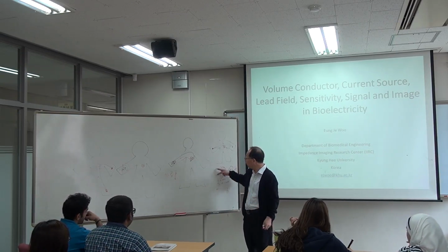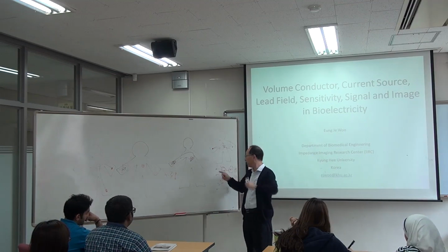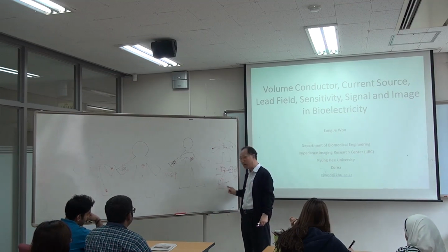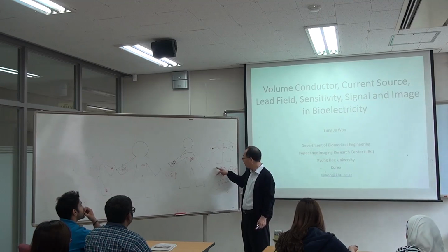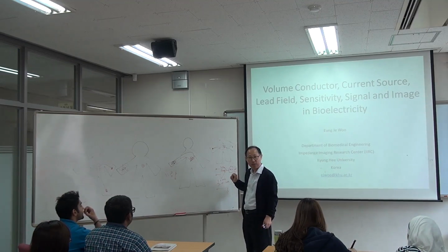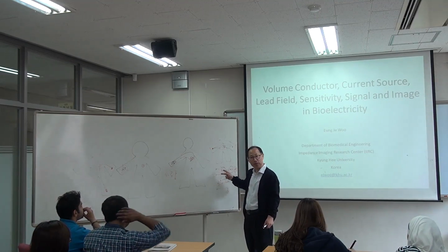So they use 2 floating electrodes and 1 grounded electrode. The body is connected to the circuit ground using the third electrode, and these 2 electrodes are used for the ECG measurement. So this is a differential voltage measurement.